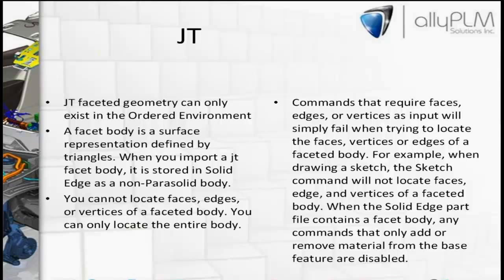Along the lines of that, obviously any of the commands that require faces or edges will fail if you try to use them on a faceted body. And if the Solid Edge part contains a facet body, then the commands that add or remove material from the base feature are just going to be disabled.